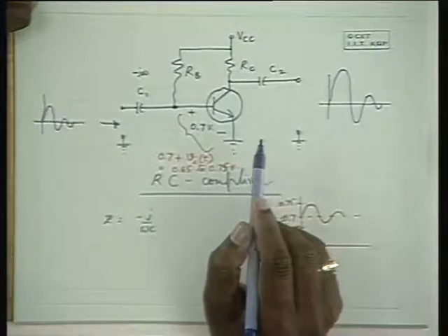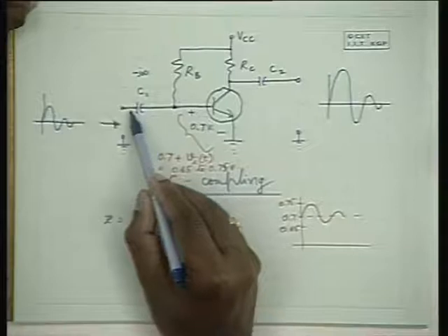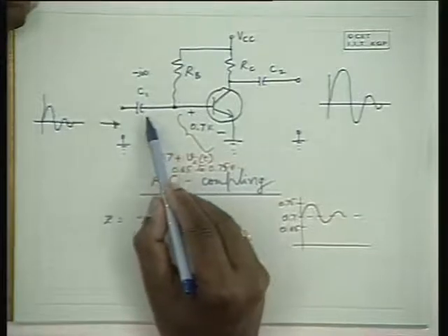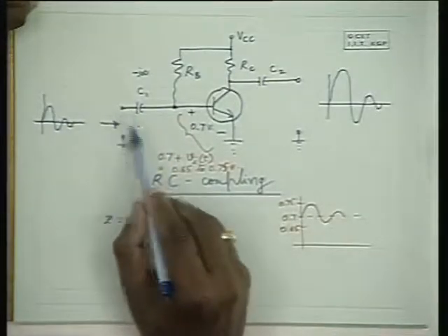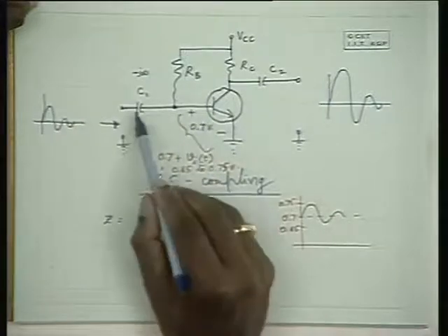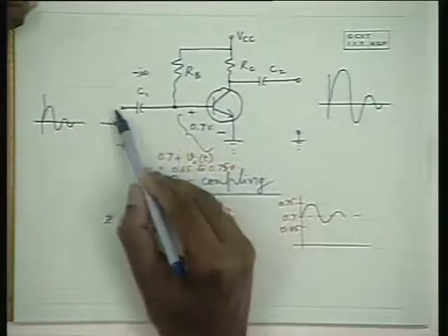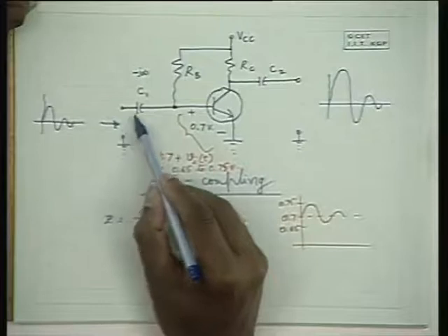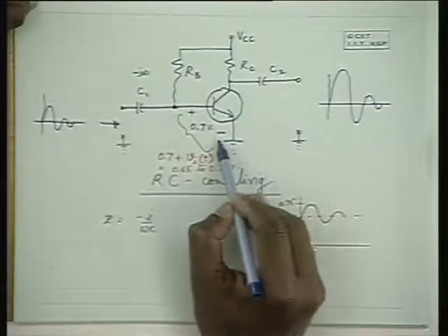Yes, there is a question. When we are applying a signal of high frequency, it acts almost like a short circuit. So why doesn't the current pass through this? Well, the question is, at high frequencies this acts like a short circuit, so why does the current pass only in this direction? Please note that it is alternating current, and we have the source on this side, an alternating signal. There is no alternating source on this side.